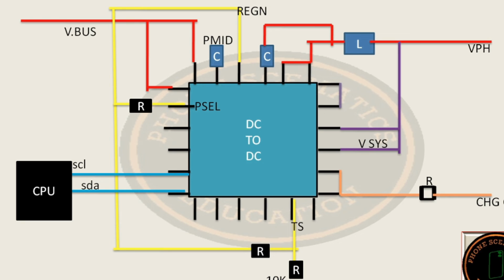These are I2C lines, right? Through this line, the CPU controls this IC. It also takes all information of this IC, like the TS line and other information, to know if the IC is working well or not. If this line had a problem... but this line is connected directly to the CPU, with no component involved in this line, so there are rare chances this line is damaged.